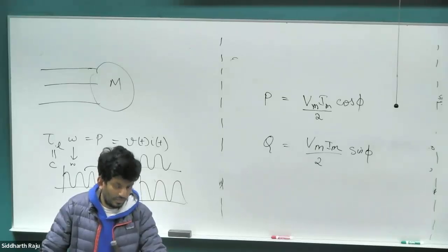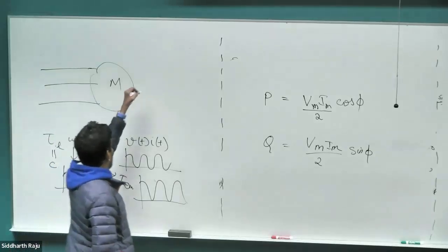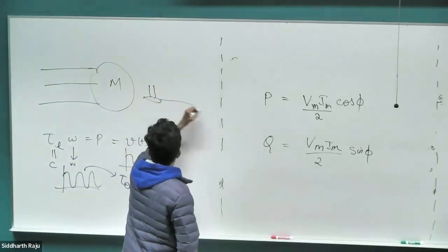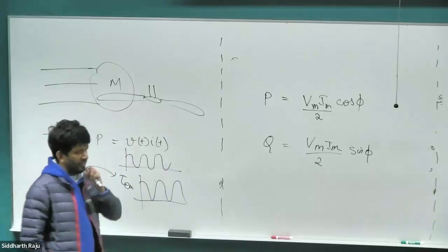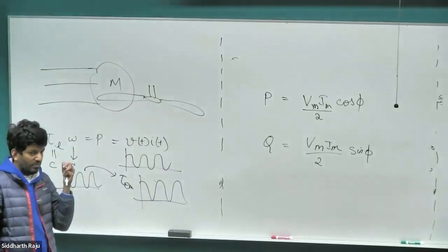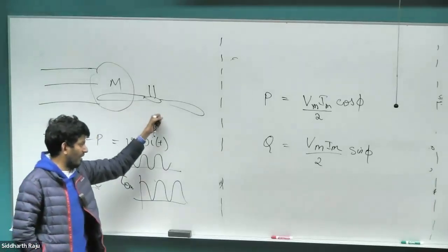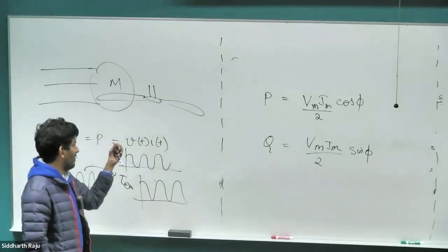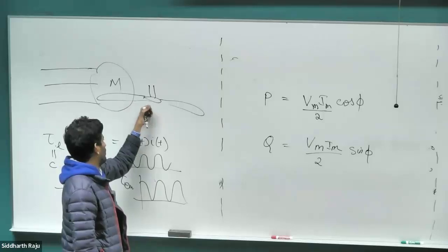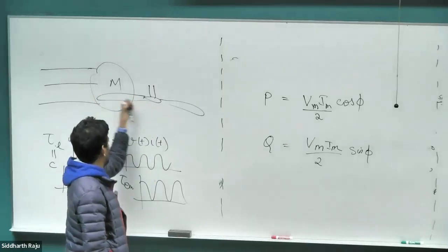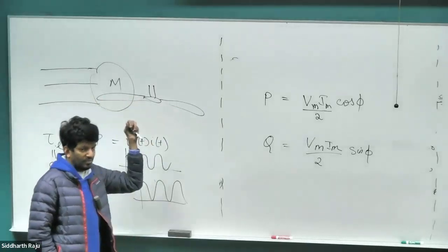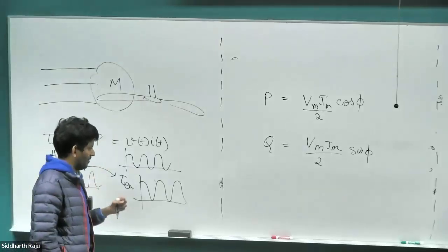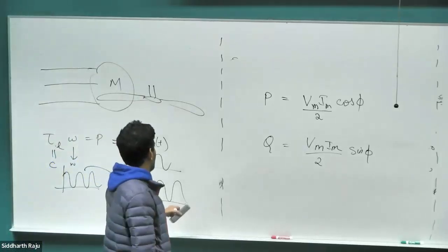Increase inertia. So the easiest way to address that in a fan is make your blades large. Right? So you have large blades in your fan, that's going to increase your inertia. That way you can reduce your oscillation. So if you have a fan at your home and it's vibrating too much, you can swap out the blades with larger ones or add some weights, make the blades heavier. That would smoothen out the oscillation that you see, vibration that you see, right?